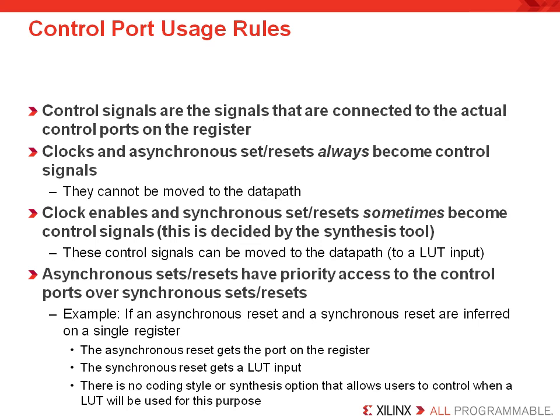You'll also need to know that the set reset port can be programmed, again, as either a set or a reset, but not both. So if you're defining a design that has both a set and a reset on a single component, then one of those will need to go to the lookup table, which means it will have to be synchronous. Unlike older FPGA architectures, there's not a separate set and reset port available on these flip-flops. So if you want both, either the set or reset will have to be generated from a LUT input and be synchronous. The set reset port can also be implemented as asynchronous, although this is not as flexible.